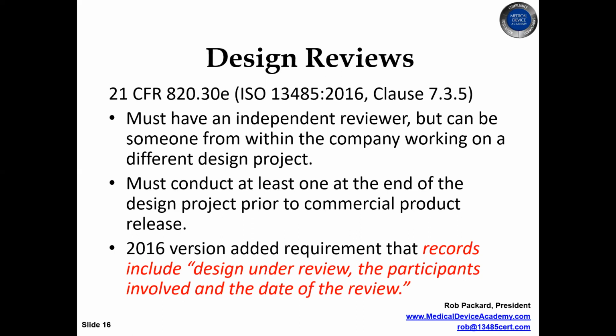This is also where you should be doing lessons learned. You could discover, hey, we thought that we were going to be able to go ahead with this project, but we need to mold some components. We didn't realize the lead time on making a brand new mold was going to be 8 weeks or 10 weeks. That's something we need to build into our plan next time. We need to release the tooling design ahead of time and order the parts way before we're going to do design verification validation, maybe even potentially before we've had a pre-sub with the FDA, because that's such a long lead time item. So you want to finalize those molded components early.